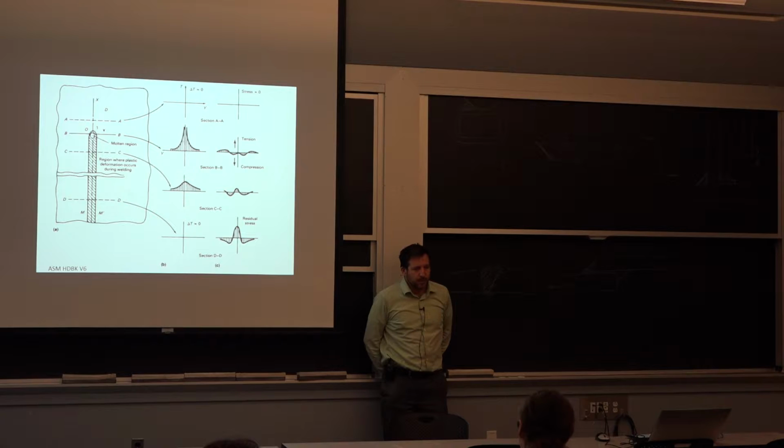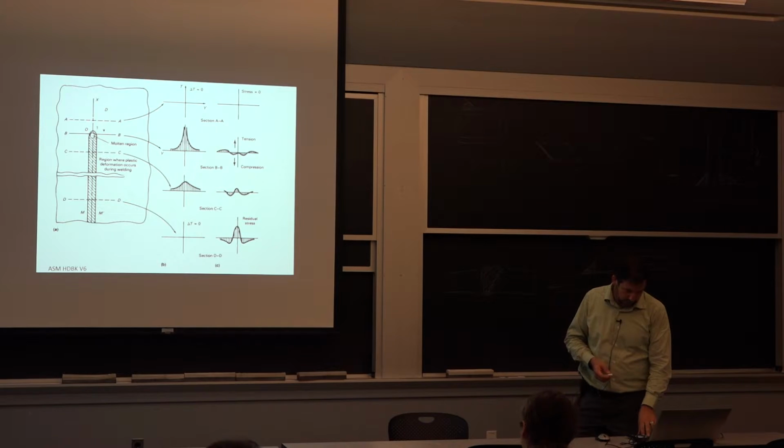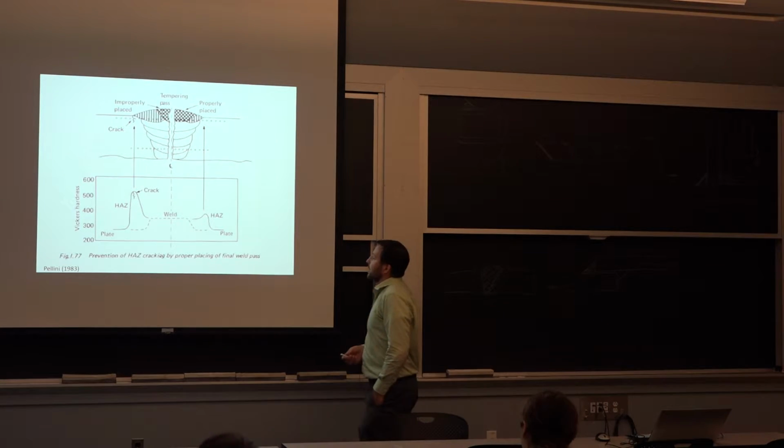If your structure, like a building, is getting loaded once, then what it means is for a little bit amount of time, you will need the ductility of the material, and maybe you'll need to get a couple % strain. That's all you need, and then it's done. That won't be a problem. But if you try to go back and forth in that zone is where you get the fatigue. And we could go through that in more detail, but it gets complicated very quickly.